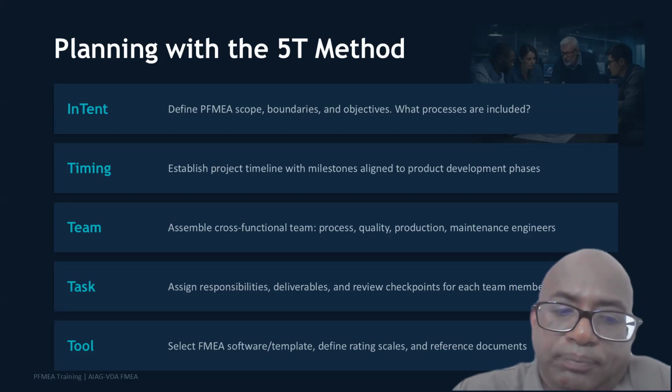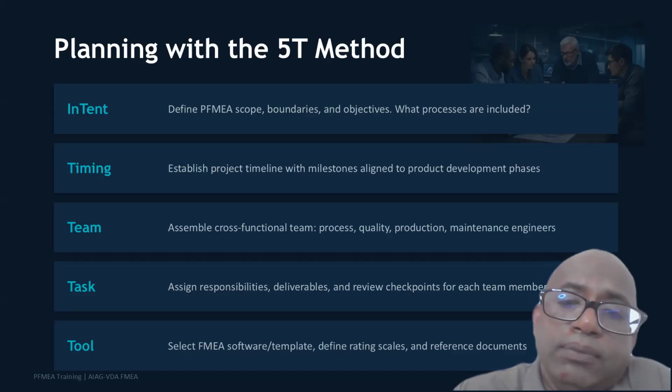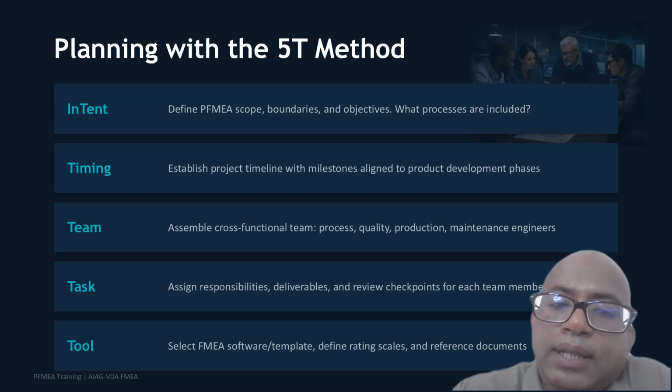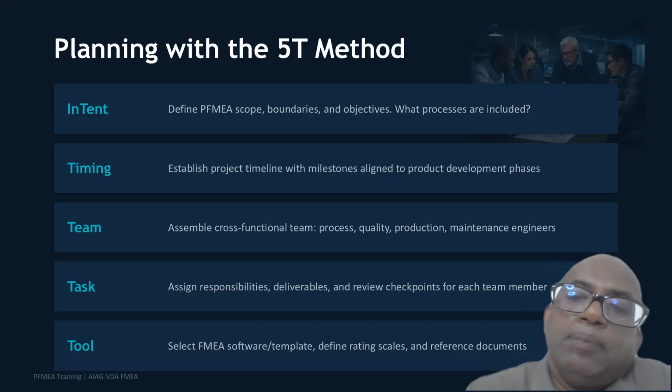Then tools. What are the tools we are going to use? Select PFMEA software and template. If you are going to use PFMEA software, you can use it, and a template also; otherwise you have to prepare the template. As I explained, you can prepare Excel templates if you don't have the particular software. I think you don't want to spend so much money buying software. You can prepare these Excel templates yourself and define rating scales, right? Then reference documents. Those are the tools you are going to use in the preparation of PFMEA.